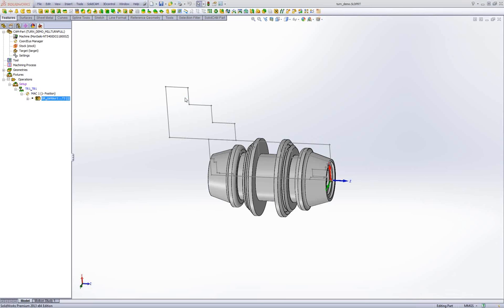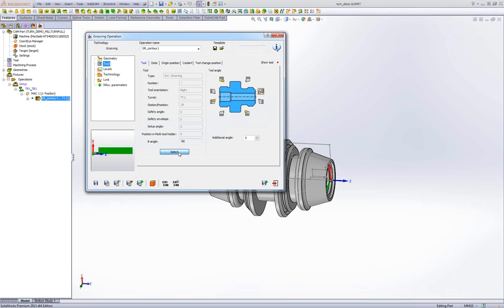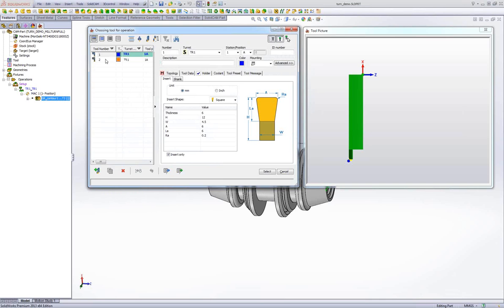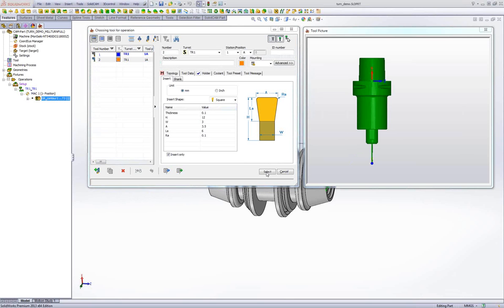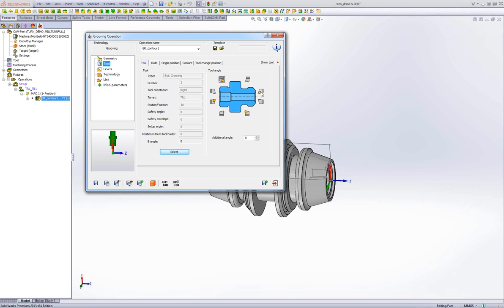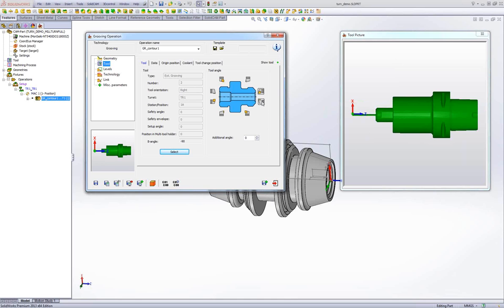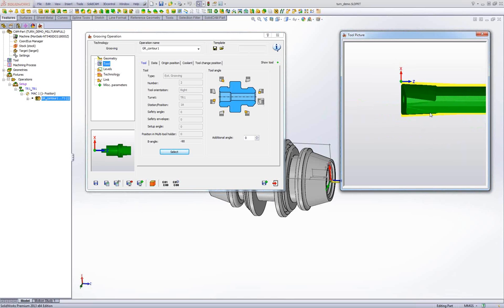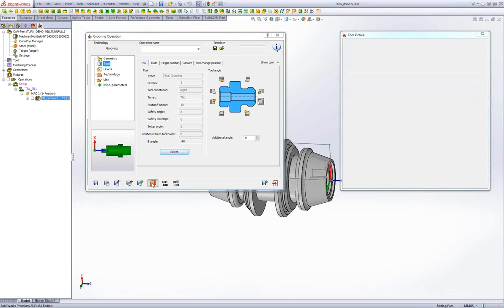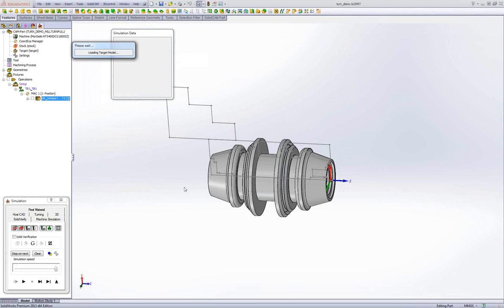Okay, now in the job, tool, select the new tool, and I want to work from the face, width, and I need to reverse with the rounded part external. I reversed, yes. Save and calculate, simulation, let's see, solid verify.